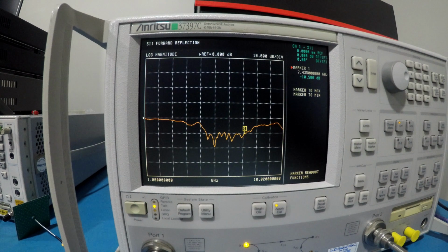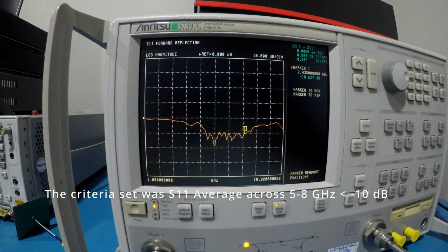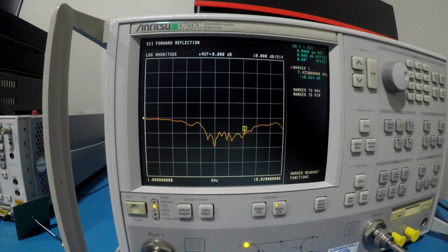Yeah, it is. It definitely is. It's radiating quite nicely for the whole bandwidth. There is no rejection in here. It takes the average of the bandwidth we're interested in. As long as the average is below negative 10 dB S11, it'll consider that good for the bandwidth. The algorithm can be further optimized where you have rejection for small signals that creep above a 10 dB return loss.